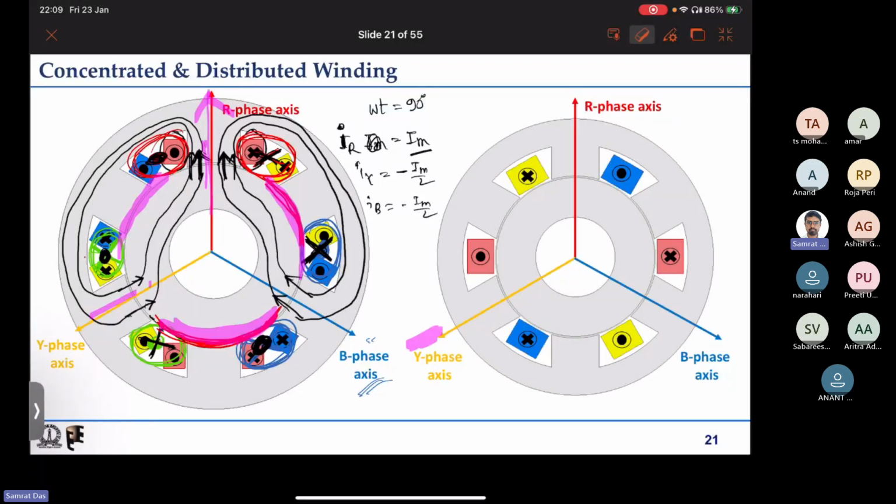For a rotating magnetic field, as the question was asked, instead of two poles for the R phase, we can have one pole only, and one pole for the Y phase, and one pole for the B phase. That is true. In this case also we are having a rotating magnetic field, only the case being that we have more harmonics, and that is away from a sinusoid.